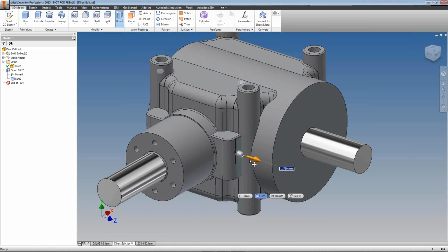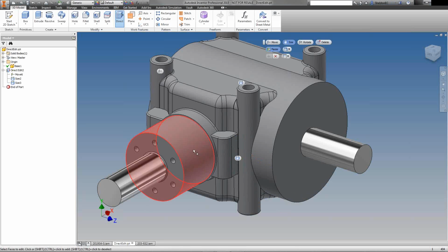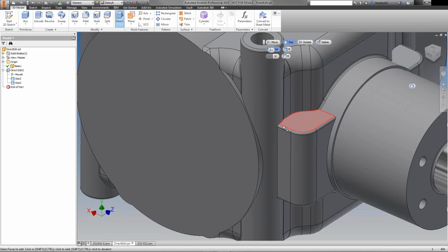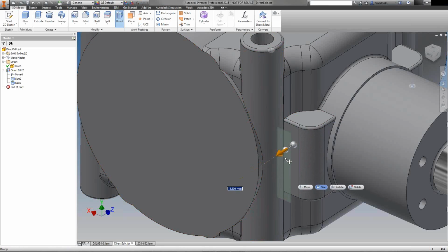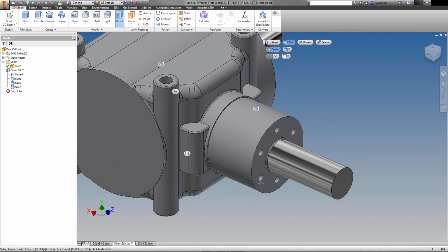Okay, maybe pull this face in here. Just -6 on that side. Hopefully what you're noticing is the other attached features that are part of the faces I'm moving are dynamically changing as well, so I'm not losing any of the fillets or the chamfers or anything like that. They're not getting bigger or smaller. I'm not having to select them at all either. So it's simply just directly moving the objects I'm selecting there.